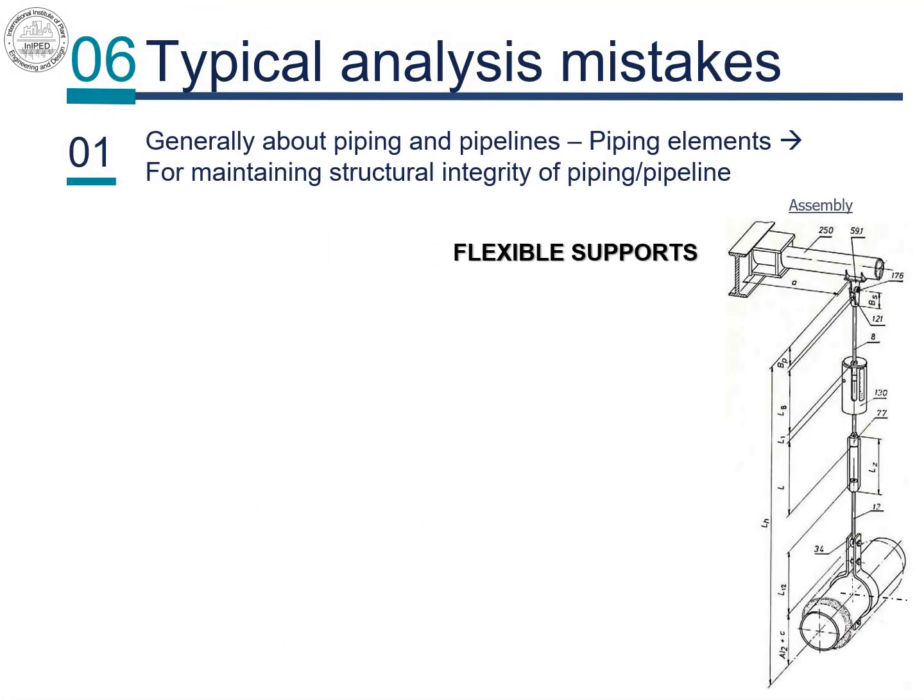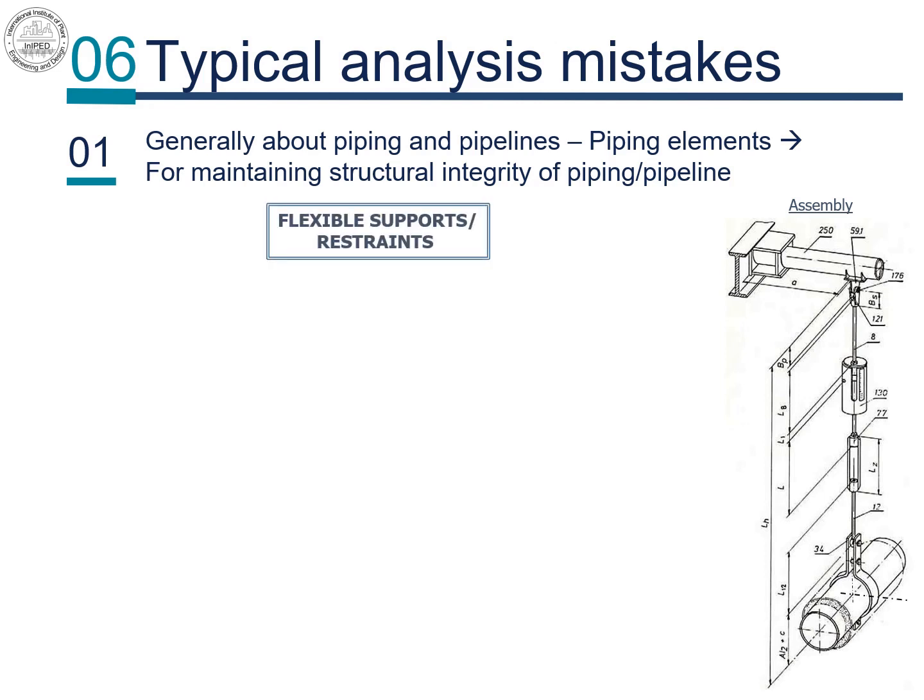With flexible supports, movement of the pipe is not restrained, but rather controlled. Flexible supports are designed around a flexible device, a spring, which enables the pipe to move while still providing support to the piping. In simplest terms, the advantage is that if designed properly, the pipe unrestrained in movement will exhibit much lower stress than a fully restrained one.